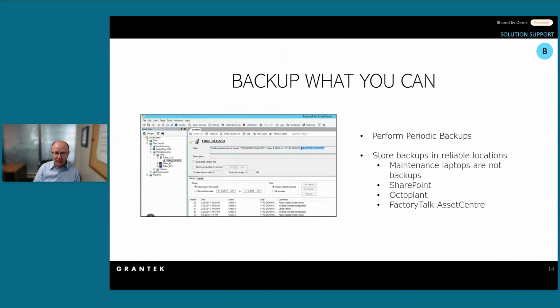Things get deleted. The guy may have a backup on his laptop that he takes home with him, and you're down next shift, and no one can find that backup, and no one knows where it is. So again, highly critical that once you know what you have, you back it up. Again, that's those VFD parameters, those PID controllers, your PLCs, your HMIs. This is great to involve your IT departments for a lot of your HMIs. If they're PC based or servers, grab images of those systems. If it fails, you don't want to be ticking around trying to figure out how to reconfigure it back to the same state it was. If you can just restore it from backup, that's the easiest way to get back up and running.